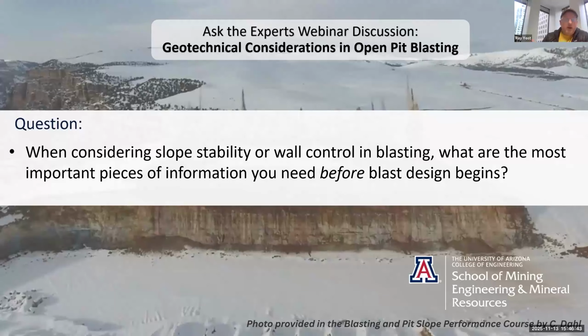Then, of course, following that is the rock. You need to know its basic characteristics. Not everything maybe, but fundamentally, how broken up is it already, the RQD or whatever measure you want to use, the hardness or strength, weathering, cementation. What is it about that rock that you need to understand to design that blast? Also if there's stratification or changes within the blast pattern, and those rock characteristics.